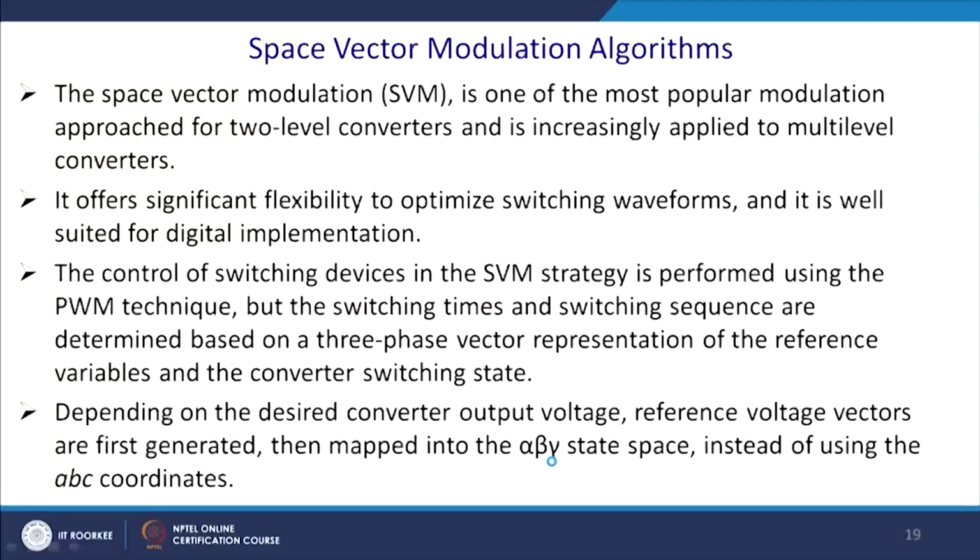Space vector modulation, or SVM, is one of the most popular modulation approaches for the 2-level converter and is increasingly applied to the multi-level converter. It offers significant flexibility to optimize the switching waveform, and it is well suited for digital implementation because it is in a 1 and 0 format.